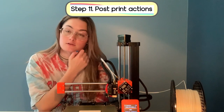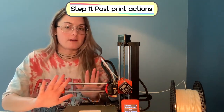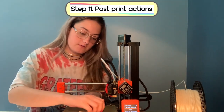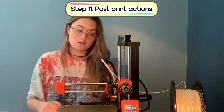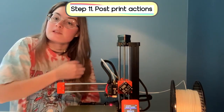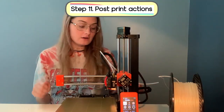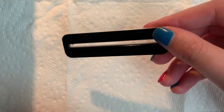Now it's time for our final step, step 11. So first, I would recommend waiting at least 5 to 10 minutes before touching the heat bed to get the print off. You don't necessarily have to unload the filament, but I would recommend it, so I'll go ahead and do that right now. It should be the same process as loading, but instead you just press unloading. And finally, remember to turn off your printer. And here we go, our finished project.